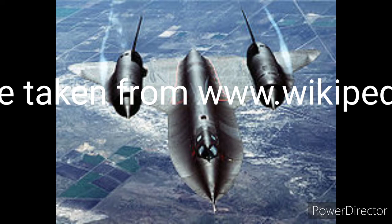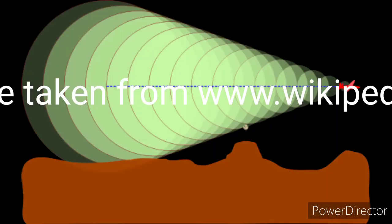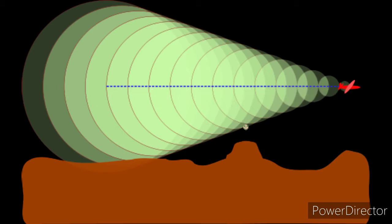This is not a viable option when compared to subsonic aircraft because the operational costs are very high, at least 3 times higher than that of a normal subsonic aircraft. The other challenge is that this flies near the ozone layer, and that creates a lot of environmental impact, like ozone depletion, etc. So typically flights are not allowed to fly at a supersonic cruising altitude due to environmental regulations.